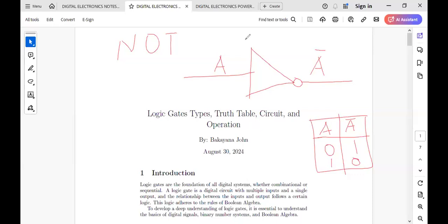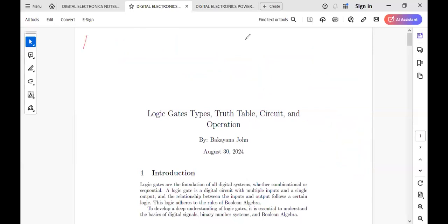So we can combine, for example, the NOT gate and the AND, and the combination comes with a very good name, NAND. NOT AND gives you NAND. The N in this case stands for NOT. In other words, after computing AND, then you invert the result you get in AND, you get the opposite of that result.